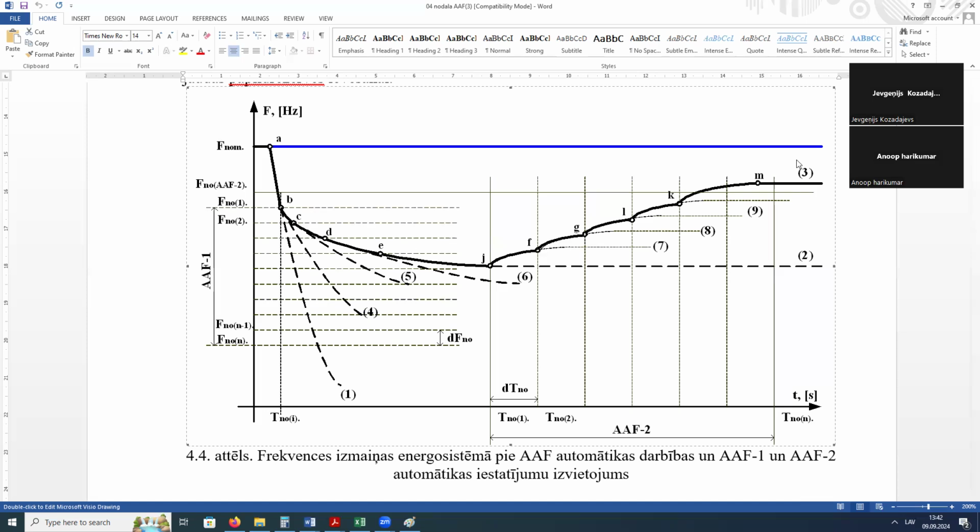In Western countries, under frequency automation stops working when the system is in balance, and restoring the frequency is a human operator task. What is not very good? Why? Because humans in these emergency situations could make a lot of mistakes, and of course human reaction speed is much lower than automatic.